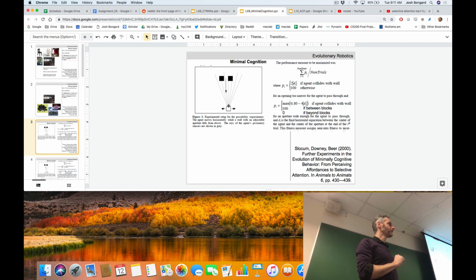So far, so good? Okay, inside this simple robot, and all the robots we're going to see in this lecture, there are CTRNNs, and the experimenters are going to allow evolution to evolve all the taus, all the Ws, all the Gs, and all the thetas. We're not setting anything by hand in these experiments.